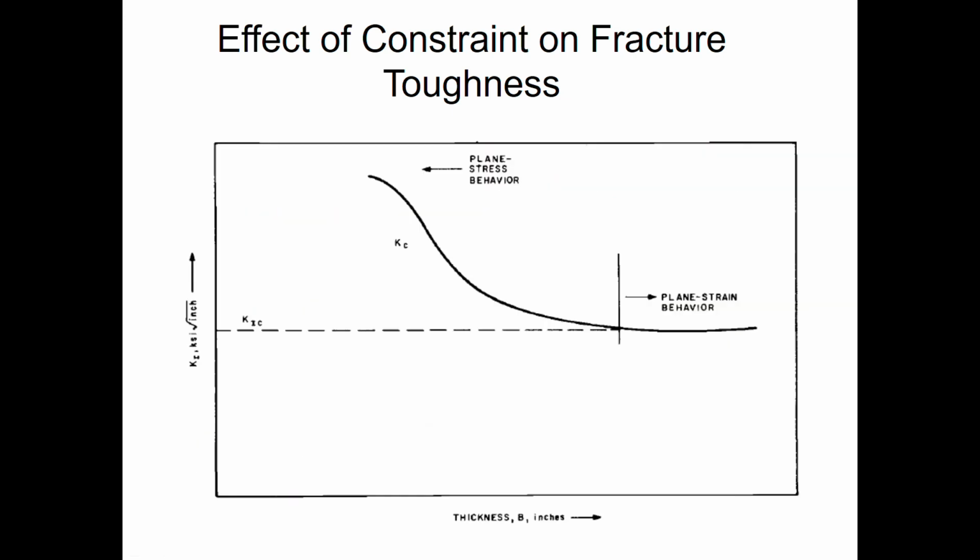Alright, this is the plot for the effect of constraint on fracture toughness. You increase the thickness, you just decrease the fracture toughness. You can see based on the trend here. If I take this value for thickness, for example 5, I have a higher fracture toughness. But if I take maybe here 30 mm or something, it is always lower compared to the other one.